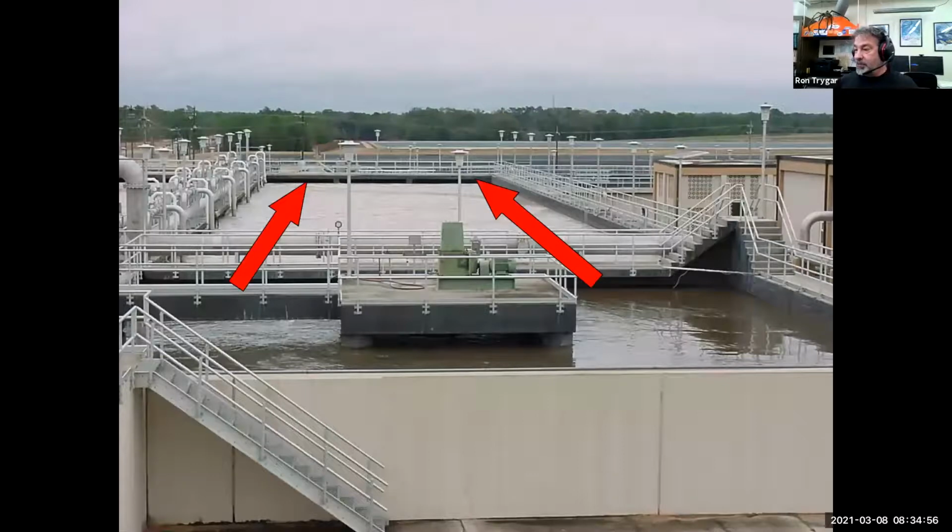So here's an example of a basin that's set up for what we call pre-denitrification. I'm going to kind of write it on the tank picture here, but this is using a process called the MLE process. That stands for Modified Ludzak-Ettinger process. So it's also known as pre-denitrification. So when we talk about pre-denitrification, we mean that we're going to denitrify first, and